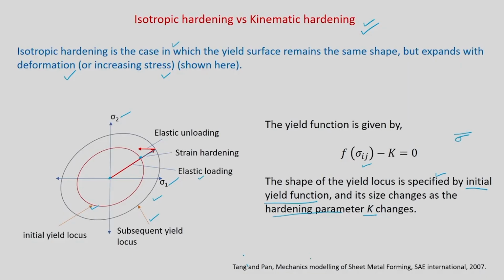In that particular slide or lecture, we wrote a similar one, and I was discussing that one part of the equation is going to decide the form of the yield equation, that is going to tell you the shape of the yield locus. On the other side, which is nothing but 2 sigma bar square equal to k, we wrote that k was going to decide the size.